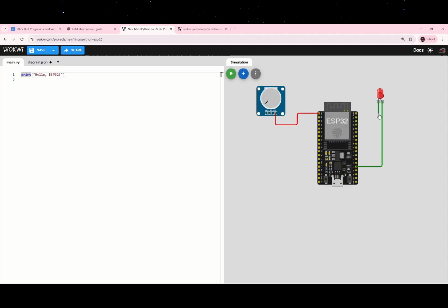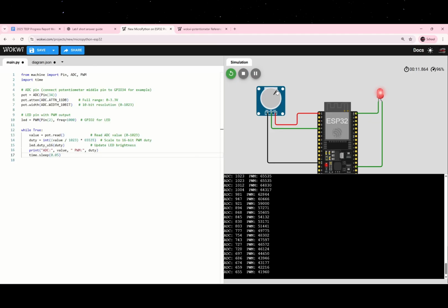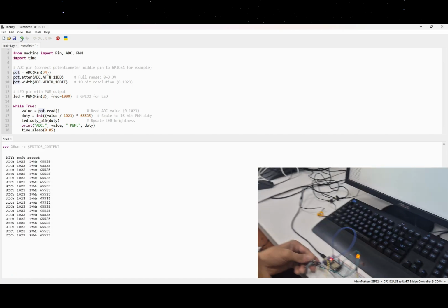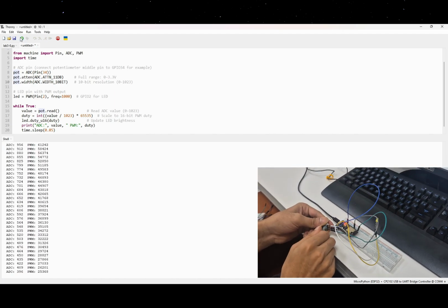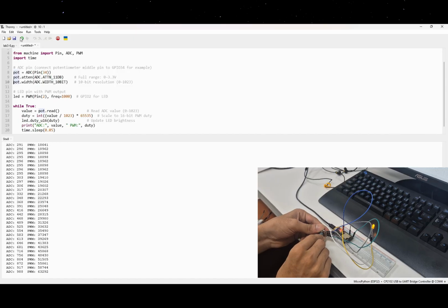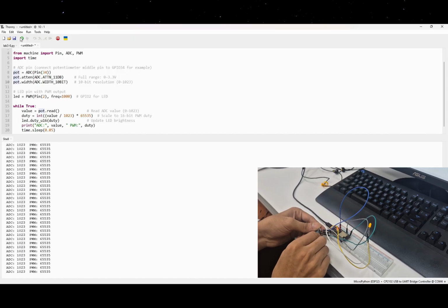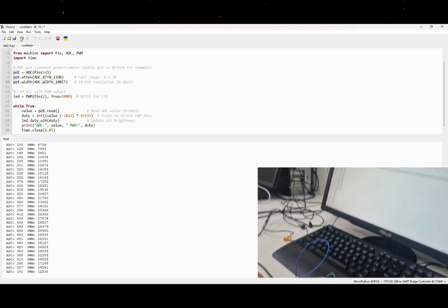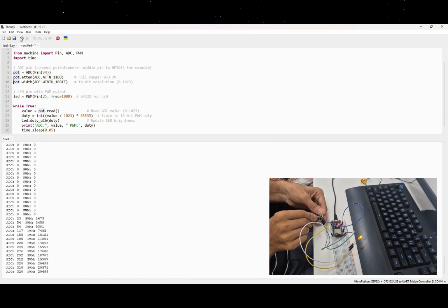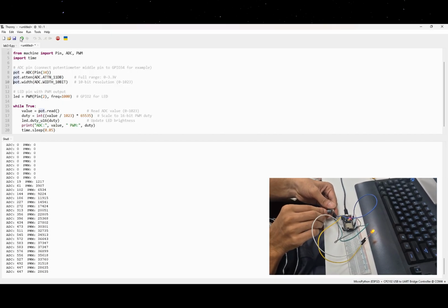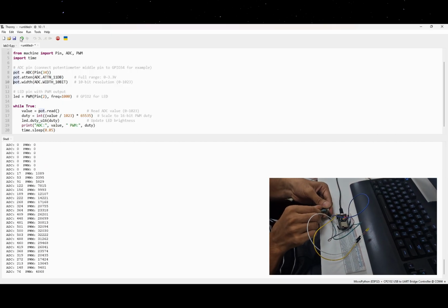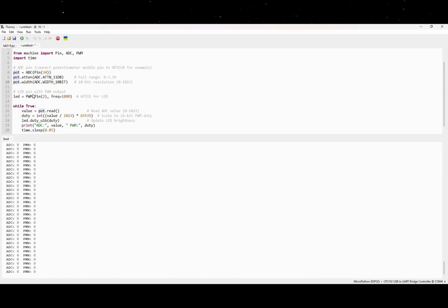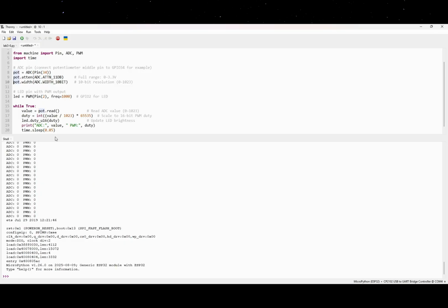In Lab 1, I explored the effect of duty cycle on LED brightness. By varying the duty cycle in a PWM signal, I could control how long the LED stays on during each cycle. A higher duty cycle means the LED stays on longer, making it appear brighter, while a lower duty cycle makes it appear dimmer. This lab helped me understand the concept of PWM in a very practical way and laid the foundation for later labs where brightness control would be more complex. It was also a simple introduction to how digital signals can be used to control analog-like behavior.